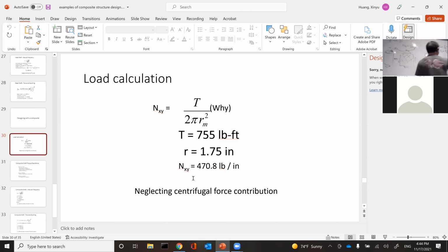And then your load here is essentially sigma axial times T, and this is sigma hoop times T. So when you have a pressure cylinder, you can solve that loading situation with your CLT code, which is loaded in the biaxial direction: tension in the axial direction, tension in the hoop direction. And the hoop direction load is twice the axial direction load, because this is a 2-times relationship.